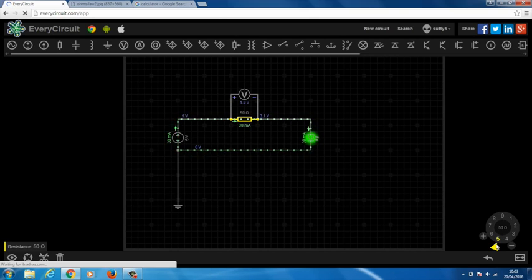If we take that resistance down a little bit more, it might blow up. There we go, it's gone. Too much current is flowing through that LED. So we've decreased the resistance enough that too much current is flowing through to the LED.